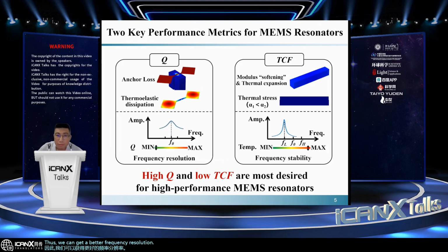The other main performance merit is the temperature stability of a resonator. As we know, the resonator's frequency will shift with the operation temperature. This is caused by two main factors. The first one is that the material becomes soft as the temperature increases.